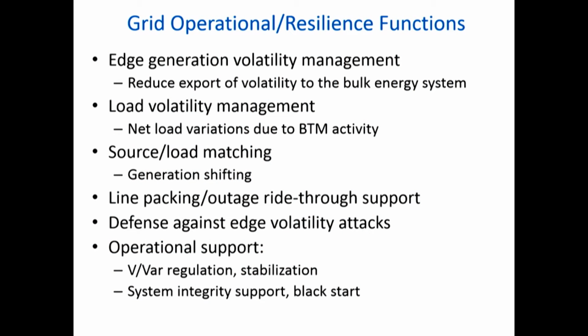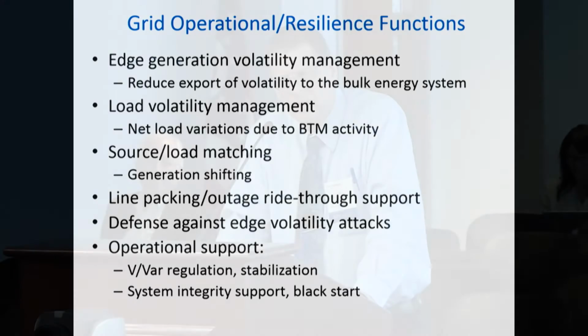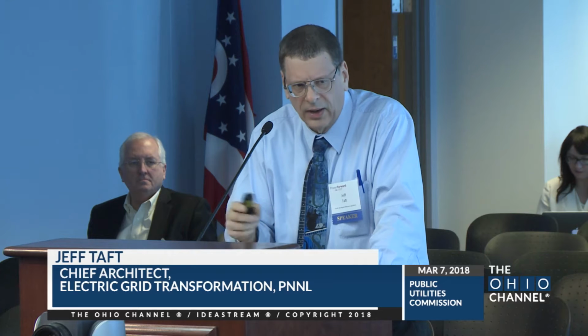Well, we've already talked about variations caused by things like solar and wind. But we also can think about that in terms of matching up sources and loads. And with demand response, we talk about load shifting in order to make things run more smoothly. Well, here with storage, you have the option to do also generation shifting. Because the problem with variable energy resources is that we can't dispatch them. They generate when they generate. And maybe that's not always best matched to the loads. So there's a lot of effort in trying to figure out how to match those up. Well, storage can actually help you do that matching. It's the buffer that evens out those things.